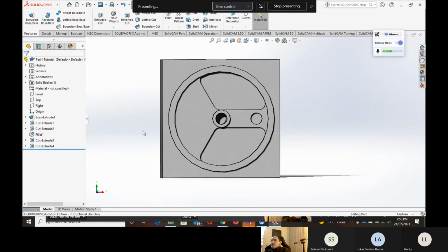For me, I tried to use these filament parts for the air conditioning, and it's semi-melted. It's almost melted when exposed to the sun or to a little bit higher temperature. So it didn't work. They told me, oh, the metal can do it. In all cases, we're going to have some porosity for these parts, so they're not going to be 100% good. Maybe 3D printing is a good thing for prototyping, but it's definitely not a very good thing till now for applications.